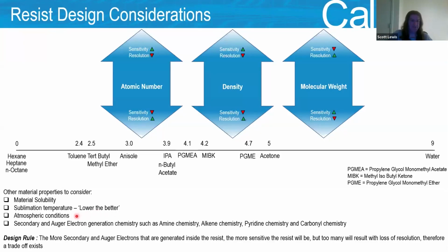Atmospheric conditions, yeah, this is very problematic, especially for resists like metal organic, because air can attack them. I worked in Manchester. I'm from Britain. It's a very, very rainy country. So water from the air can basically attack the resist, and so it starts to, in my case, etch, or it starts to write. So that is problematic.